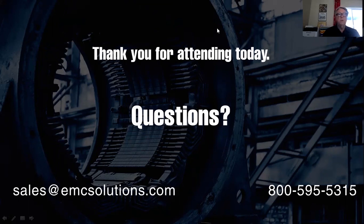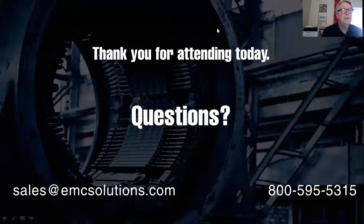This says, what would you recommend for a system with multiple 150 horsepower to 500 horsepower drives? That's a very interesting question, because we have multiple drives, and so that makes me think, oh, we should use an active filter. But as you can see, the drives are very large, and because they're large, that active filter is going to be large, and it's going to be expensive.